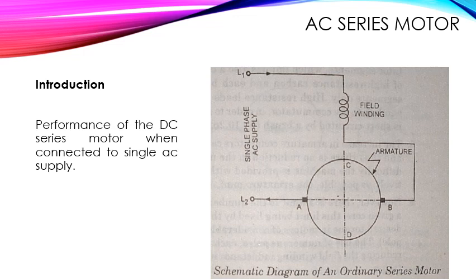The rotor or armature current also lags behind the applied voltage, but because of its fewer turns, the angle of lag cannot be large. So the time phase difference between the flux and the rotor current is considerable, and since the torque developed in an AC motor is proportional to flux, rotor current and the cosine of the angle between the two, the torque developed is further reduced.